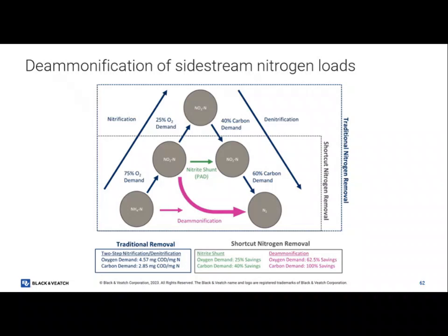I don't want these guys to eat it all. So you've got to have a sensor in here to read ammonium. Because essentially you're saying, okay, I want 50% of it, and I want 50% of this. So I've got to have equal parts of each to do this. So you essentially have sensors in there controlling air. If you're looking at an air cycle in these, it's probably going to do like this, because it's trying to do just enough air to get 50%. And then lastly,